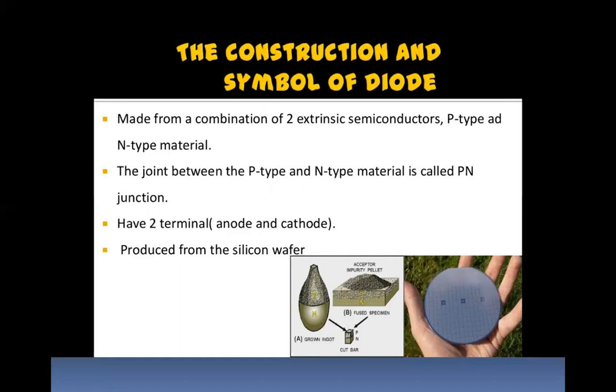But because boron has only 3 valence electrons, one is lacking. One vacancy will be created, waiting for one more electron to form a pair. That vacancy is called a hole, which is positively charged. And the material we form is called a p-type material.